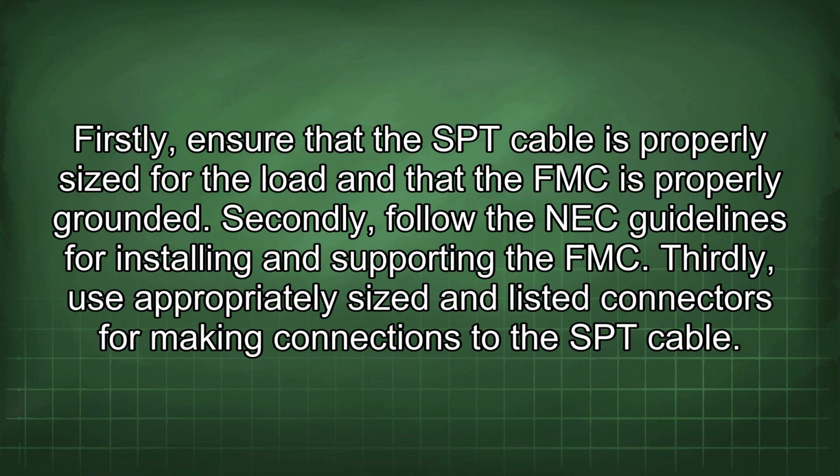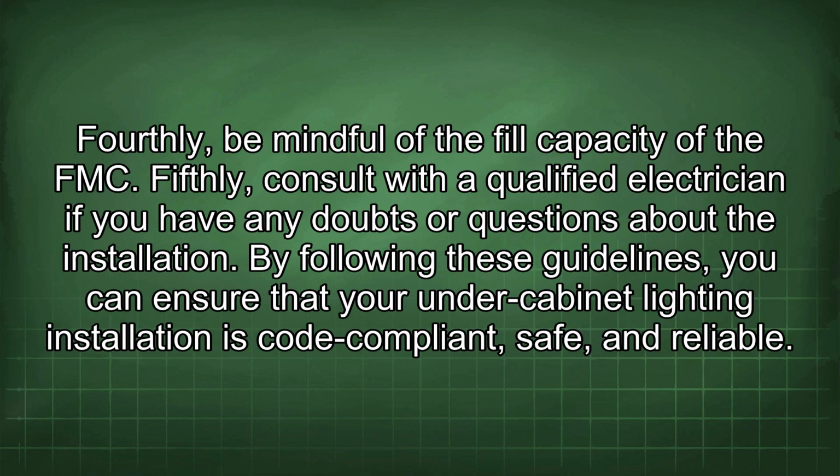Firstly, ensure that the SPT cable is properly sized for the load and that the FMC is properly grounded. Secondly, follow the NEC guidelines for installing and supporting the FMC. Thirdly, use appropriately sized and listed connectors for making connections to the SPT cable. Fourthly, be mindful of the fill capacity of the FMC.